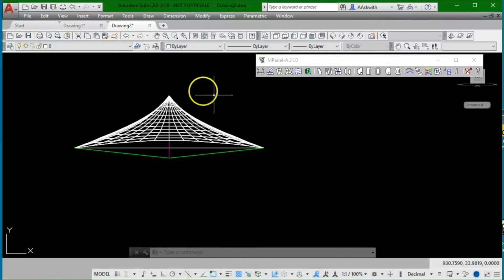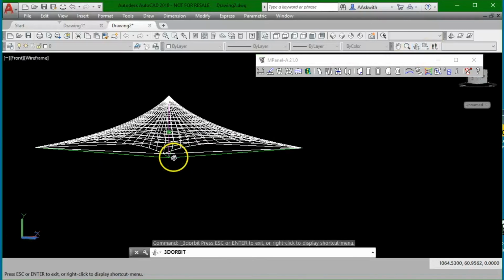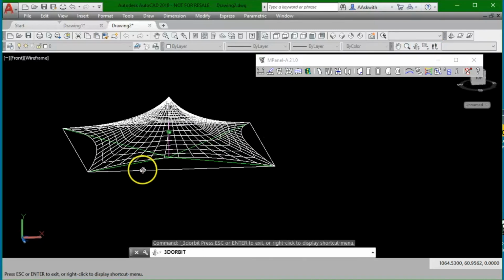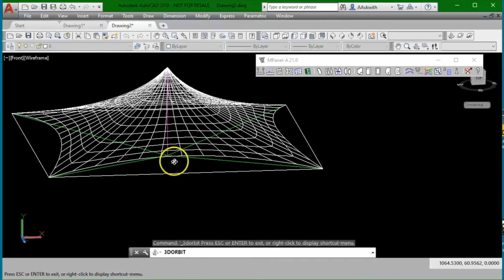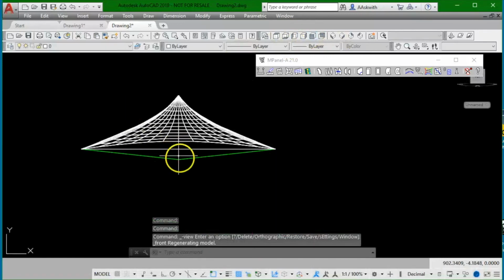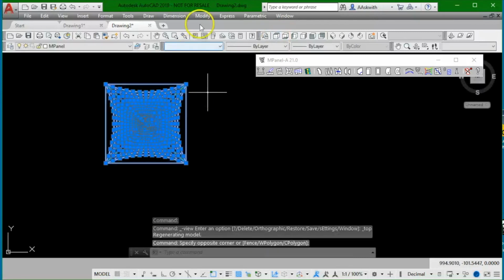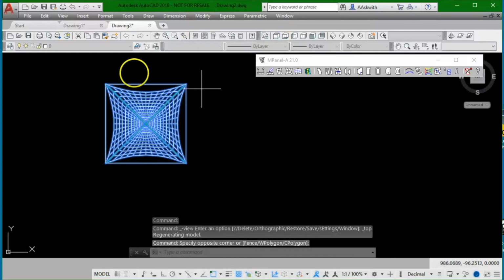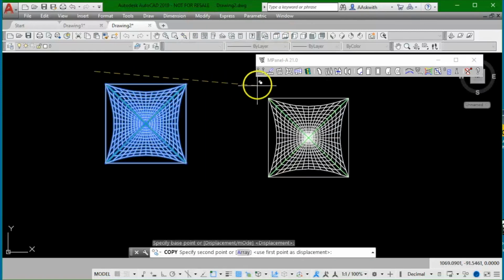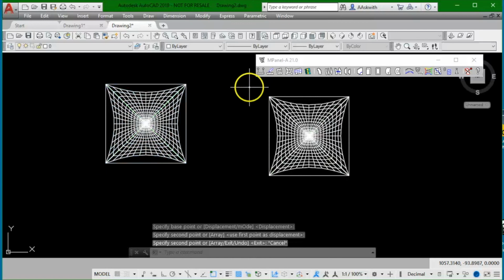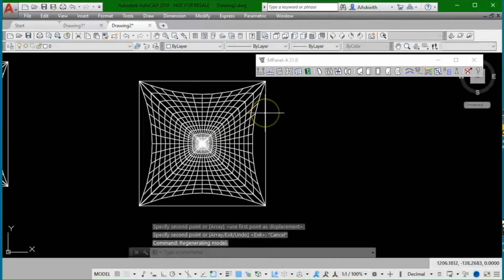Once we're happy with both the shape of the tent, the structure, and with the amount of droop on the cables in here, then we could look at the tensions that are being generated in those links. Typically we'll find that those tensions are much higher if we go for a small drop in the pole position.